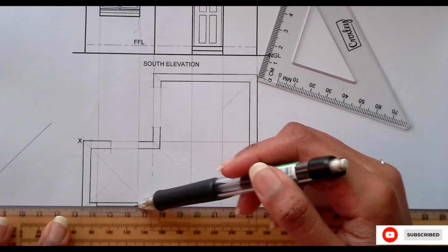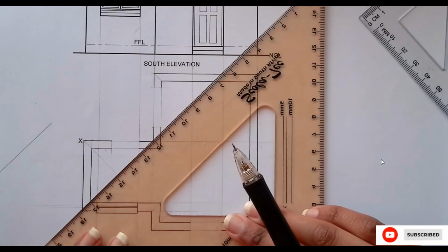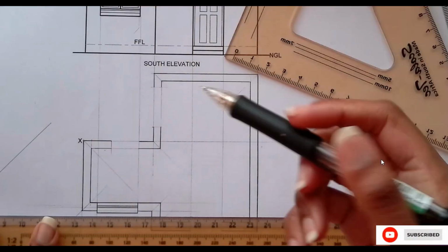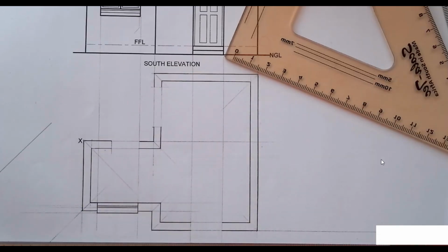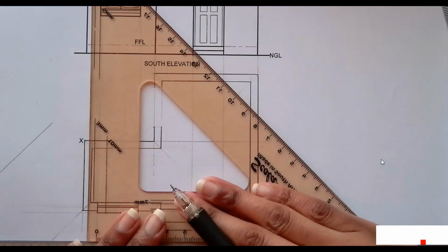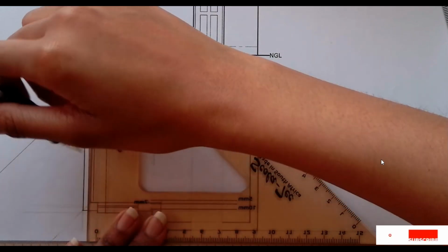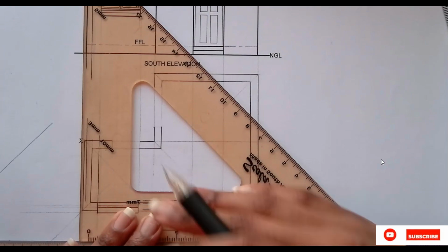Okay, you have to use very light lines. If you can't draw construction lines, you might as well just go there and measure. Very extremely light lines. So 45-degree lines, I mean all lines to the 45. Where they touch the 45, you take them up. Once again, extremely light, and try to be very, very accurate.